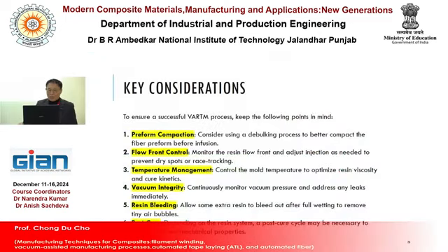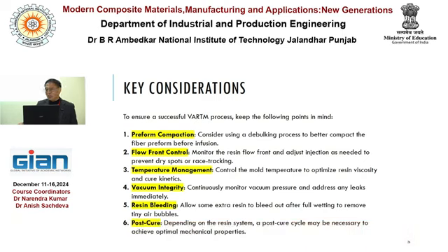And temperature management is that resin viscosity must be well taken care of. So viscosity, liquid viscosity, severely depends on temperature. So if the manufacturing temperature is different from local to local, that means each part's viscosity and flow characteristic will be different.